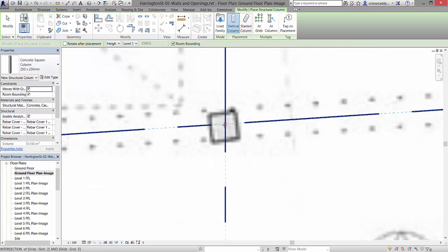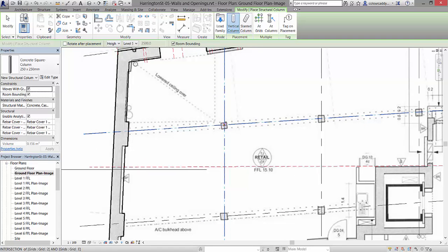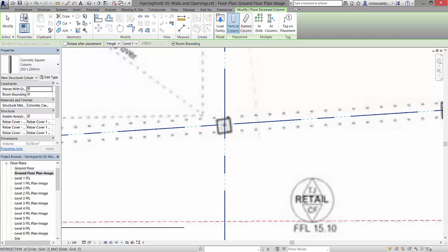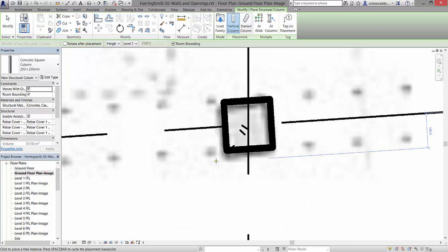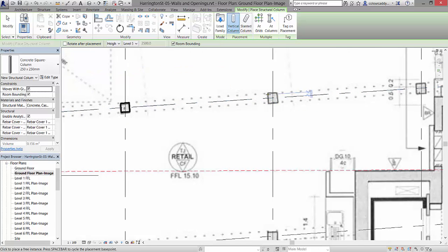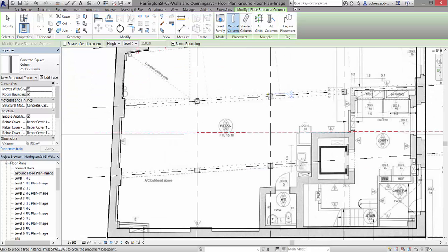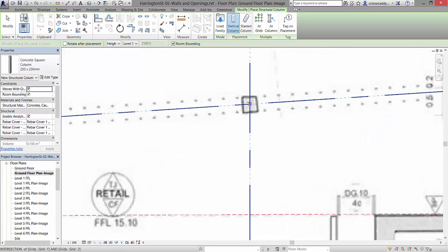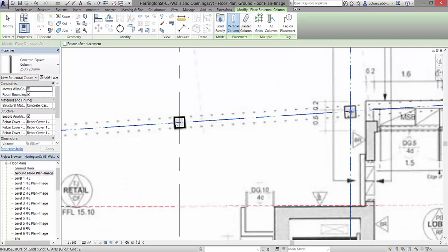And now, ordinarily you could use at grids, but here I want to make sure the angle is right. So I'm going to just place one initially. I think it's going to be worth checking. Yep, it is. It's actually not too bad. So I can just keep going and placing on the intersections there. At grids I think isn't necessary here. It's not going to save you much time. So I'm just going to click onto each intersection and make sure they do follow the angle of the angled grid, not the vertical grid.